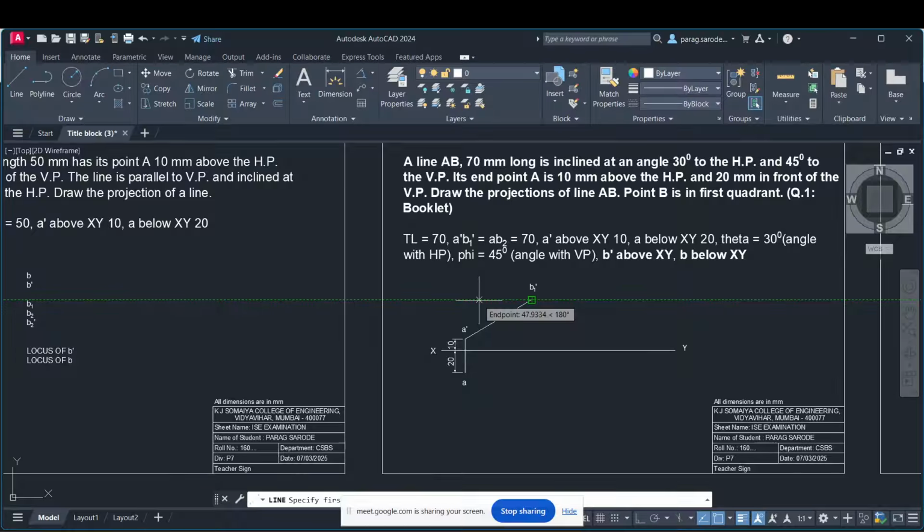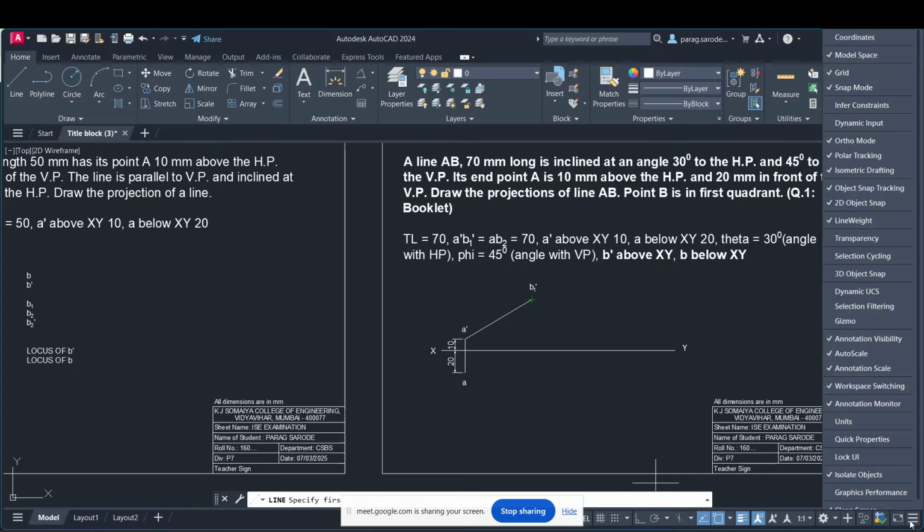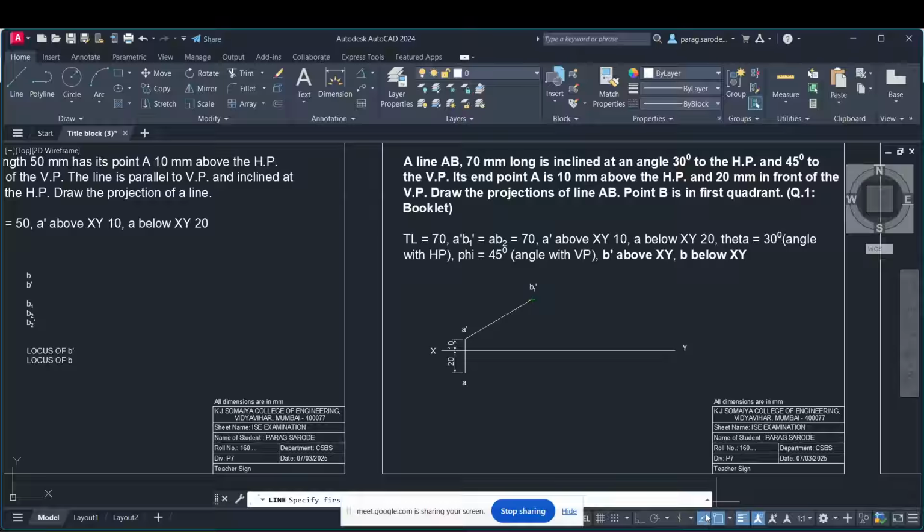Now you can see this green color dotted line is appearing on the screen. Why is it appearing? Because besides this O snap, you can see this object snap tracking is on, right? Now on the customization menu, you can see above the 2D snap, object snap tracking is tick marked. If I remove this tick mark, it will disappear from the screen, correct? One more thing, even though it might have been checked here, it needs to be enabled. How do you ensure that it is enabled? See this. Once it is clicked, it is highlighted in sky blue color. It means it is on.